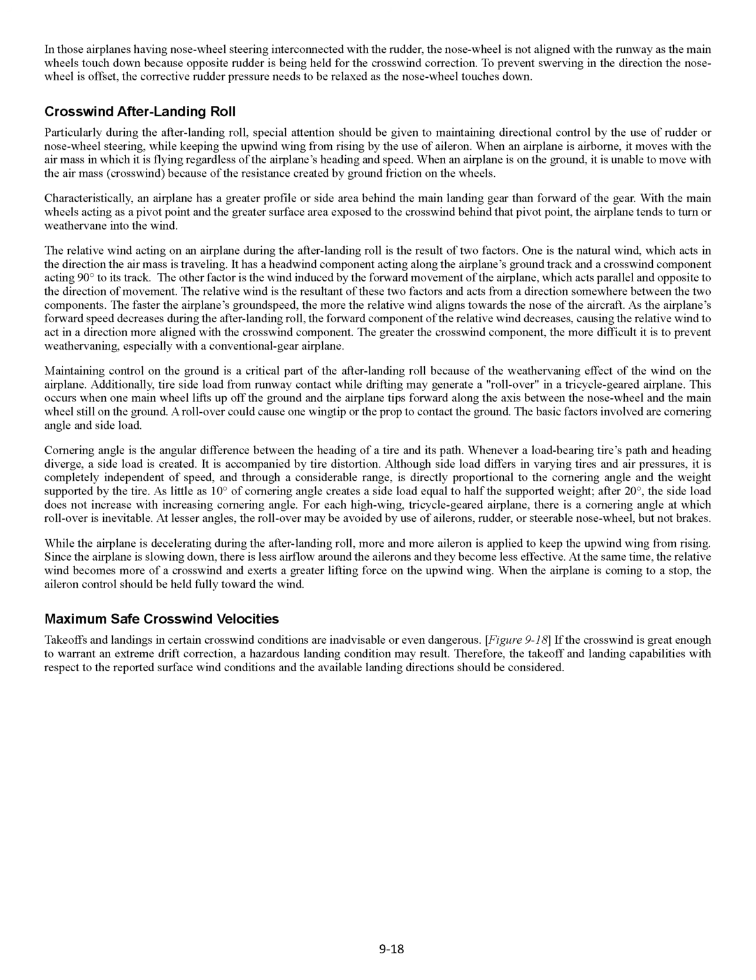The basic factors involved are cornering angle and side load. Cornering angle is the angular difference between the heading of a tire and its path. Whenever a load-bearing tire's path and heading diverge, a side load is created. It is accompanied by tire distortion.